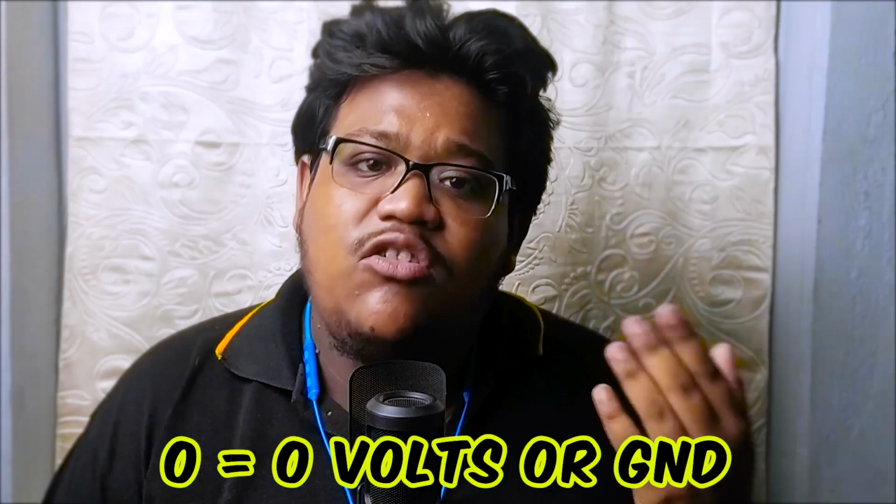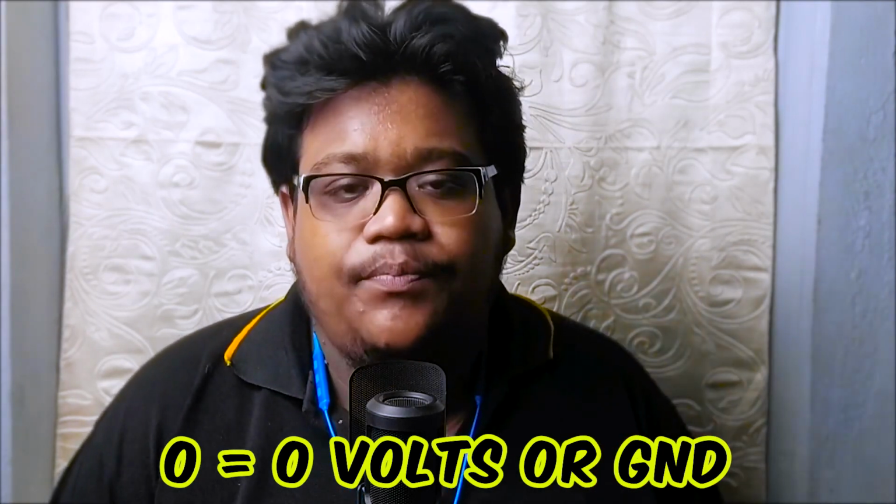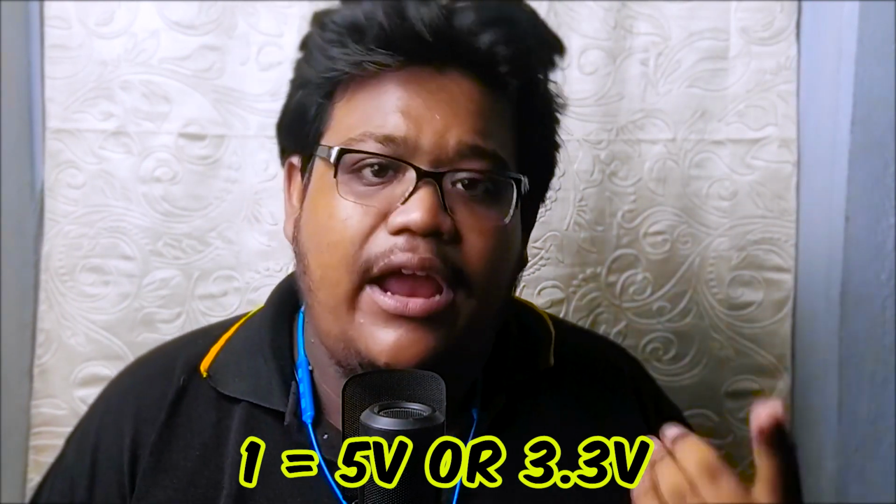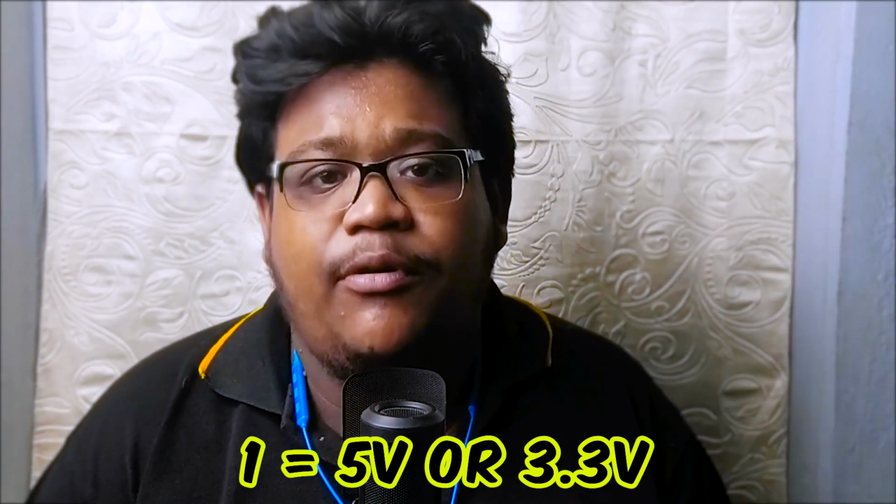As I have said before, we have two states in digital type of input and output, that is 1 and 0. So what does it mean in the real world, what is 1 and what is 0 in terms of voltage, power, current, etc.? 0 means 0 volt or ground, and 1 means, for some microcontrollers, 5 volt, and for some microcontrollers, 3.3 volts. So it is defined by the logic level that 1 will be 5 volt or 3.3 volt. So here we heard a term, logic level.